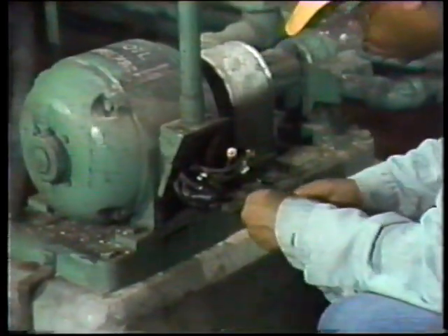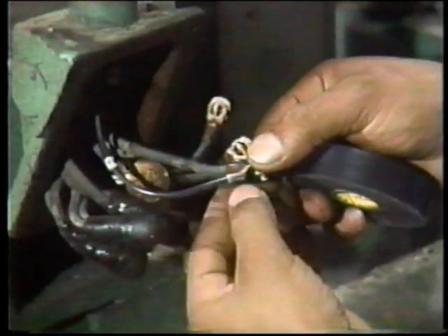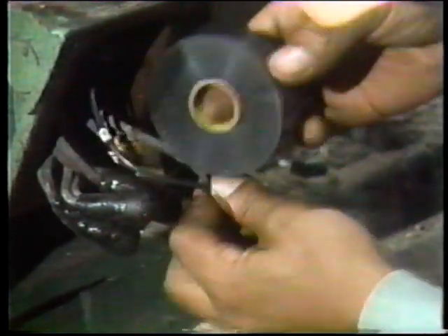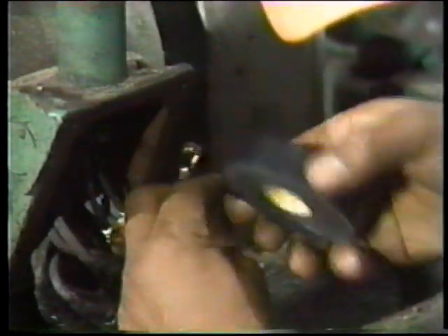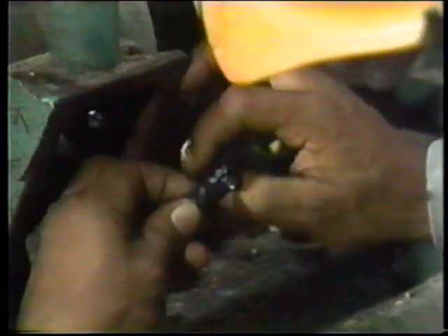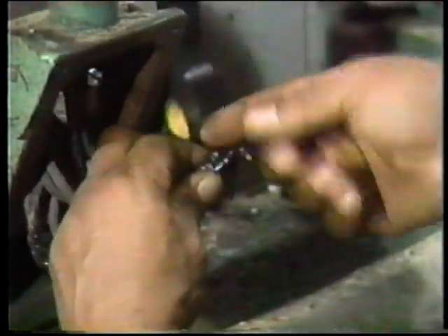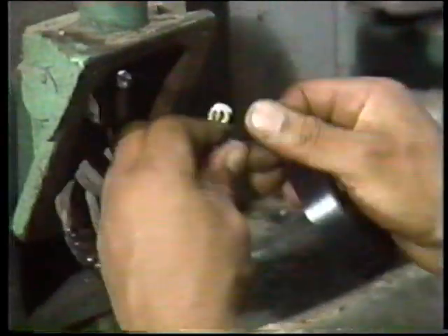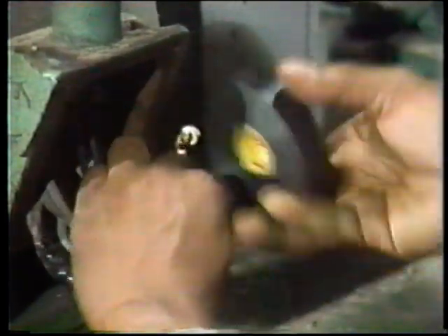Bill will put a minimum of 3 layers around the connection to ensure that the insulation will be both mechanically and electrically strong. He applies extra layers of tape around the end of the mechanical connection. This is done for mechanical protection so the metal edges of the motor housing won't cut and damage the termination. Bill keeps light tension on the tape as he works. The light tension on the tape prevents air spaces between the layers of tape and provides a strong electrical connection. Once he's finished rebuilding the insulation around this connection, he'll go on to insulate the other 2 mechanical connections using the same procedure.